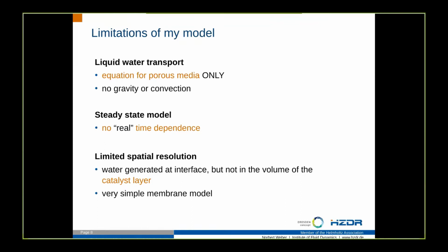The model which I presented you is, in general, what I would name an engineering model, which means it includes quite a lot of simplifications, but it is possible to model a complete cell or even a complete stack. And I think the most important limitation is the liquid water transport, which I told you already. So the equation holds only for the porous media, but it does not include the liquid water transport in the channels. Secondly, it is a steady state model, so no time dependence. And lastly, the spatial resolution is somewhat limited.